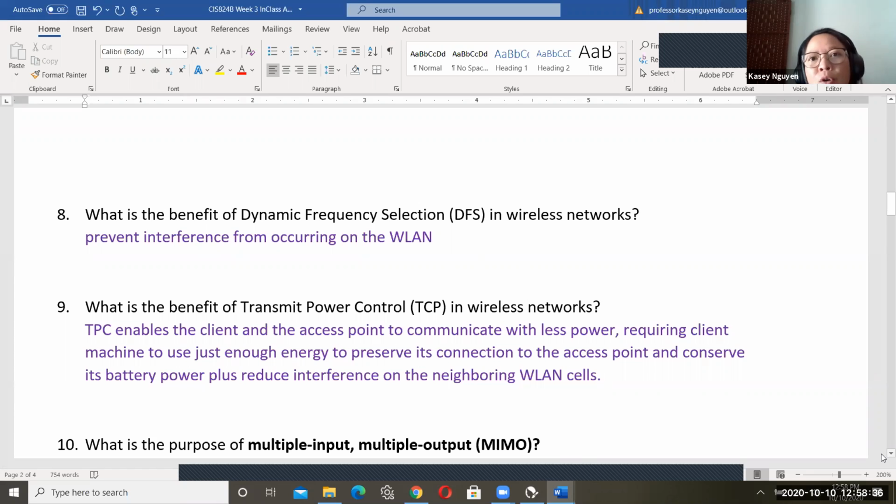And you saw your cordless phone is at 2.4 gigahertz. Microwave oven is at 2.4 gigahertz. So when you have a lot of different electronics together in the same space, you often see that there's interference. It would have degrading signal, or sometimes prevention of signal being received or transmitted. So this is why when you physically station your smart TV and your phone and different things in a room, you should think about this, okay?